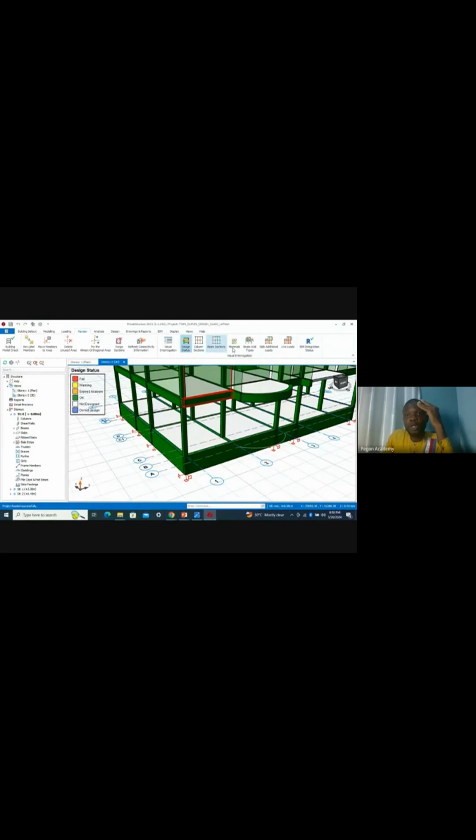You can apply loads, like I said earlier, beam wall load. You can apply slab additional loads. If you have any additional load, let's say for example, you're designing a factory that is going to have a lot of machines on the slab, then you want to apply additional load to take care of these components. Now you can also apply wall live load, right?